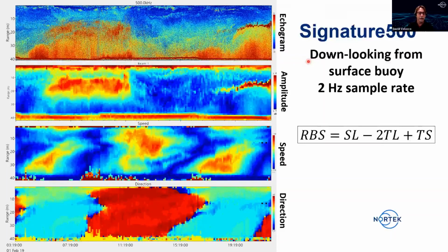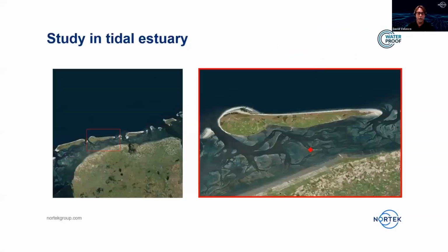But I also find it interesting that all of the near-bed information, or most of it, where you have the highest concentration, is effectively missing from the amplitude of the slanted beams. Mostly because the sediment towards the top is getting attenuated, and then the signal isn't really getting down to the bottom as well as it can. So, for example, all of this information over here is effectively lost over here, similar to this part of the tide here. So clearly there are some benefits that can be gained with more modern systems.